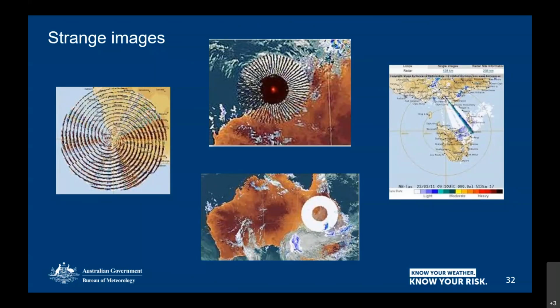So the radar picks up that strobe, and we quite often get interference from things that don't comply to the Australian regulations. We also get interference from cruise ships, military operations, and the like. So if you see any strange strobes on the radar, generally speaking, that's electromagnetic interference from an external source. And those with the newer radars filter those out a little bit better than some of the older radars. So that's something to look forward to with the new radars.